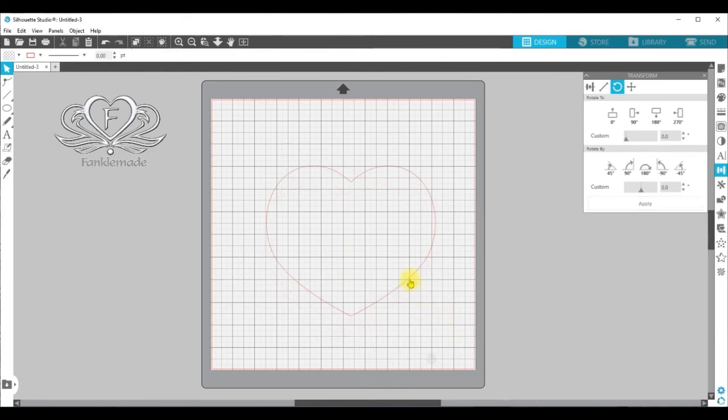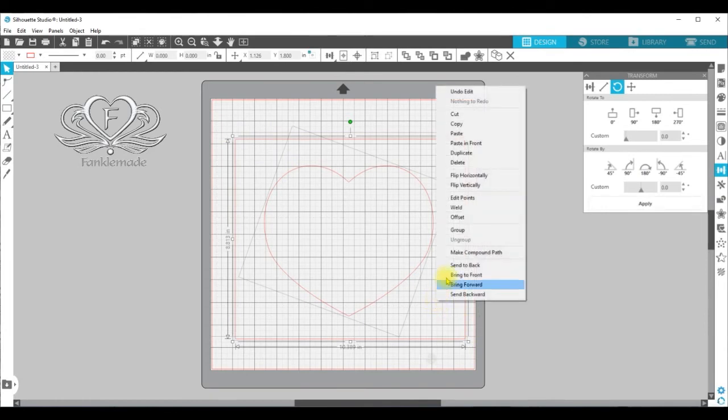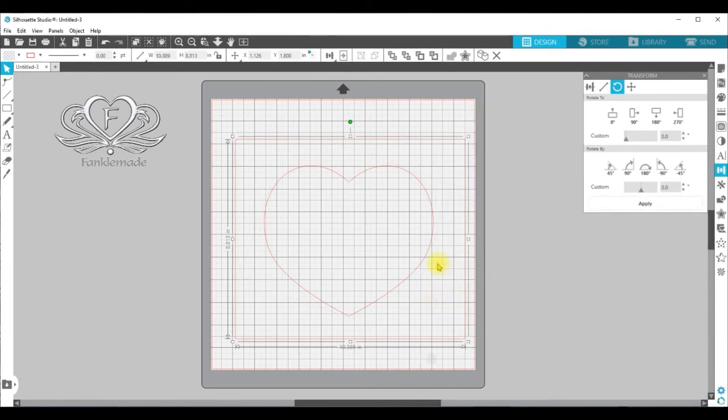To get around that, you need to create another shape around this one. Just go over to the drawing tool, select whichever one you want, it doesn't matter for this, drag it out around it so it fully surrounds the object, select them both, right hand click, make compound path, right hand click, release compound path, and just that has made the selectors around the object vertical and horizontal around it.